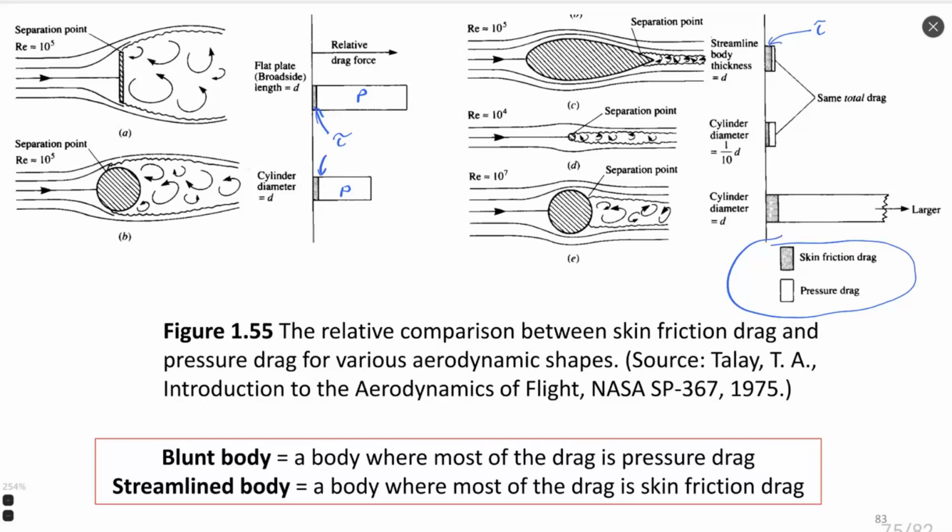Okay, and for an airfoil, the biggest source of drag is skin friction, and the smallest source, very small here, is the pressure influence on the drag. This relation between pressure and skin friction influence on drag gives us the possibility to determine two different types of bodies.